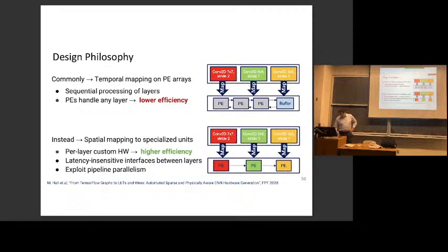The design style that HPipe uses between these PEs is a latency-insensitive communication channel. So that's basically a data flow architecture. It's one of those streaming data flow models with ready and valid signals, basically. Like the ready valid signaling that you're using in assignment 1 and assignment 2 is what it's using as well. And it has FIFOs at the input to each of these PEs so that it can buffer up some data. So it's using exactly one of the programming models that we talked about.